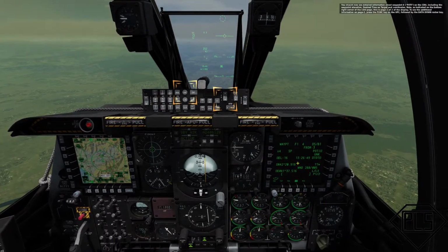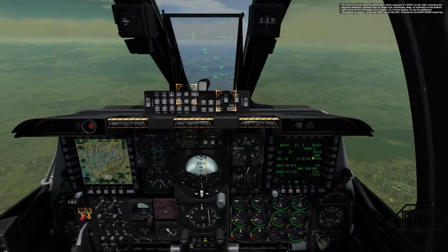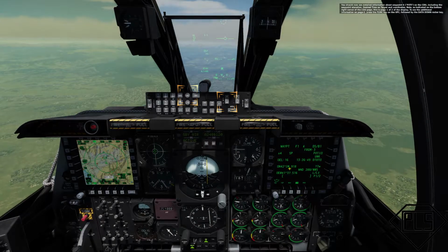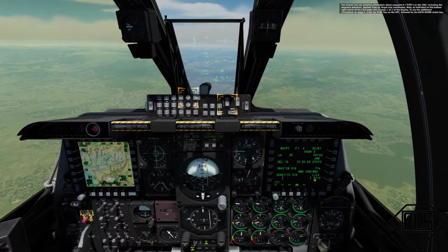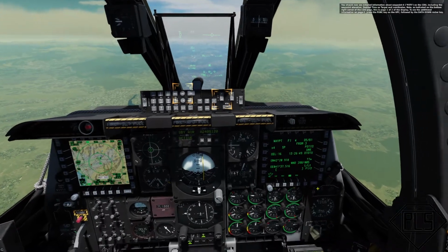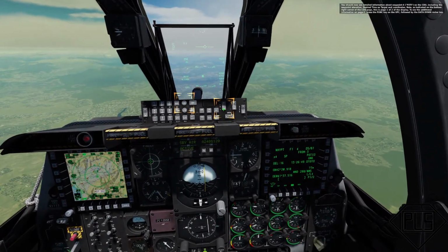You should now see detailed information about waypoint 4 Pote on the CDU, including the waypoint elevation, desired time on target, and coordinates. Note, as indicated on the bottom right corner of the CDU page, this is page 1 of 2 of the display. To see the additional information on page 2, press the function key on the UFC followed by the data down rocker key.